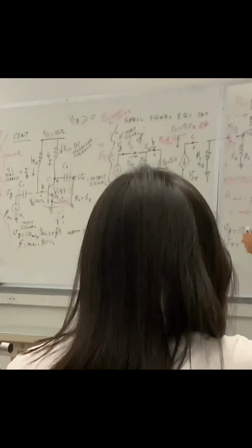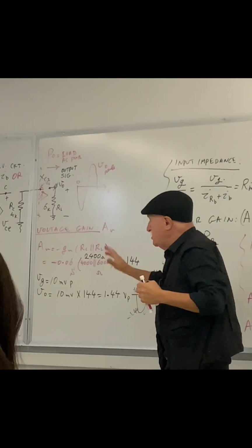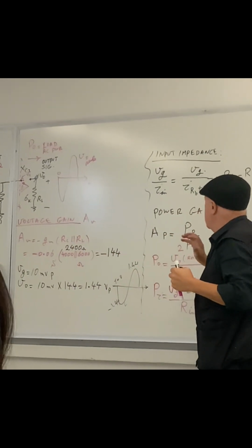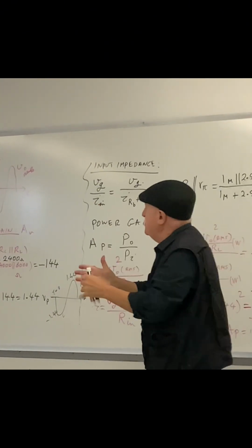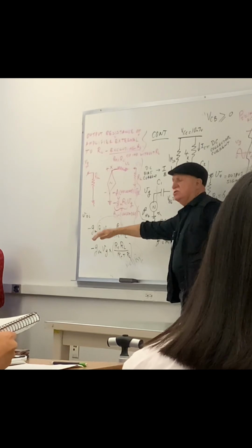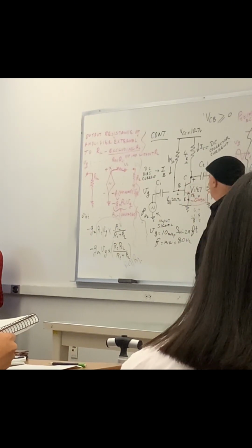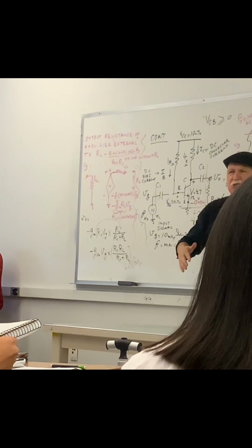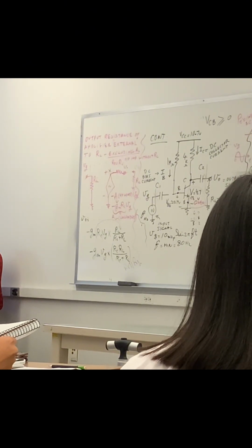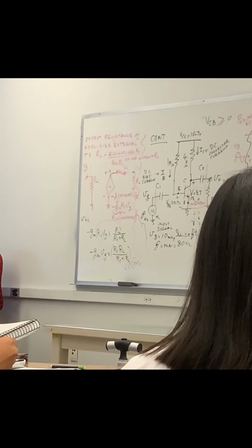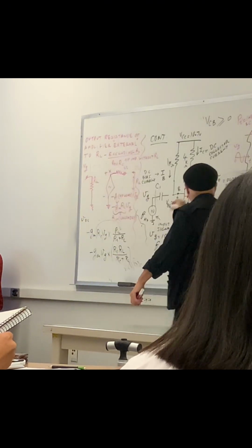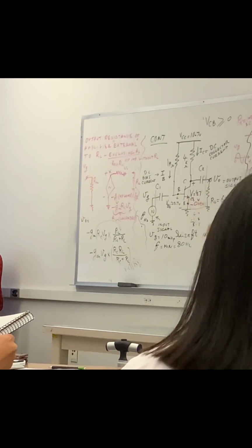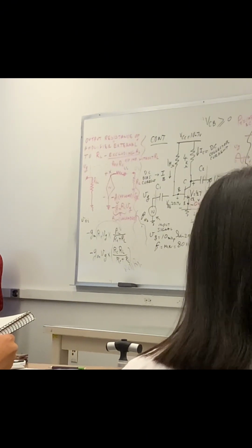We talked about the input impedance, power gain, voltage gain, loaded voltage gain, and then we talked about dB power gain and the model for the amplifier, only excluding the source, excluding what will be connected in here, whether it is a load resistor or something else, maybe another amplifier, which the input impedance of that amplifier, the second one coming, will reflect as if it's the load for the first one. And what will happen, gentlemen, is called coupling loss.